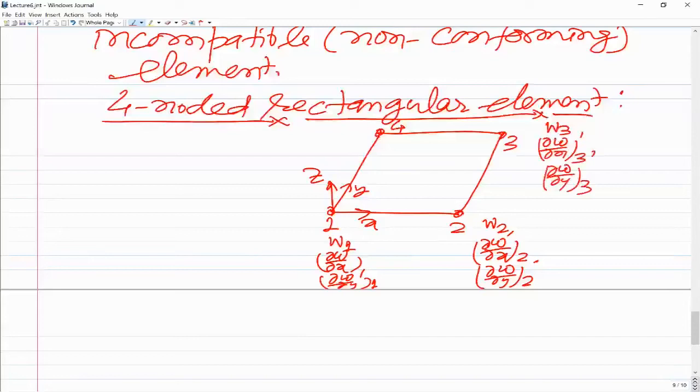So now based on this, total elemental degrees of freedom are going to be 12, because 3 degrees of freedom at each node, that is all the 3 primary variables, and 4 nodes. So when we assume an approximate solution, that should have 12 terms in it. So that is 12 unknown constants in that, and there would be corresponding 12 terms.